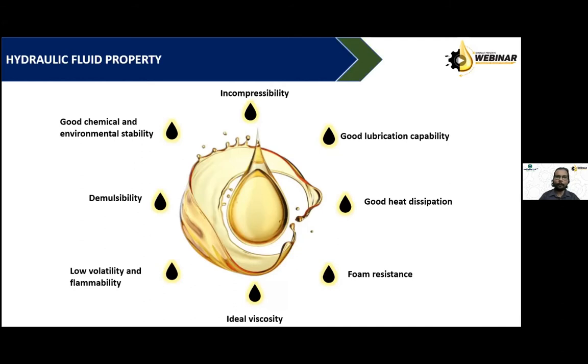Oil should have sufficient quality to demulsify. Emulsification is mixing of water with the oil, or mixing of gases in a few cases. So even if water enters into the oil, it should have the property to get separated from the water, and due to density difference, water will settle down into the bottom in most of the cases.